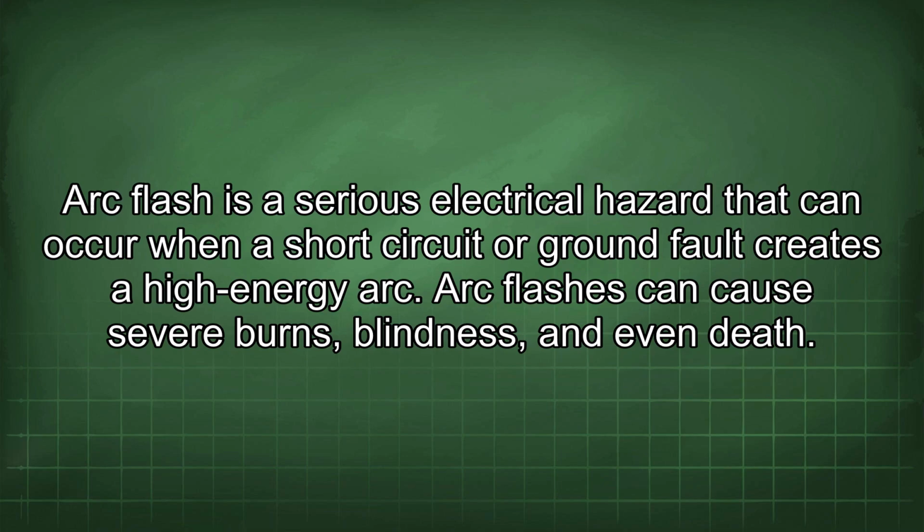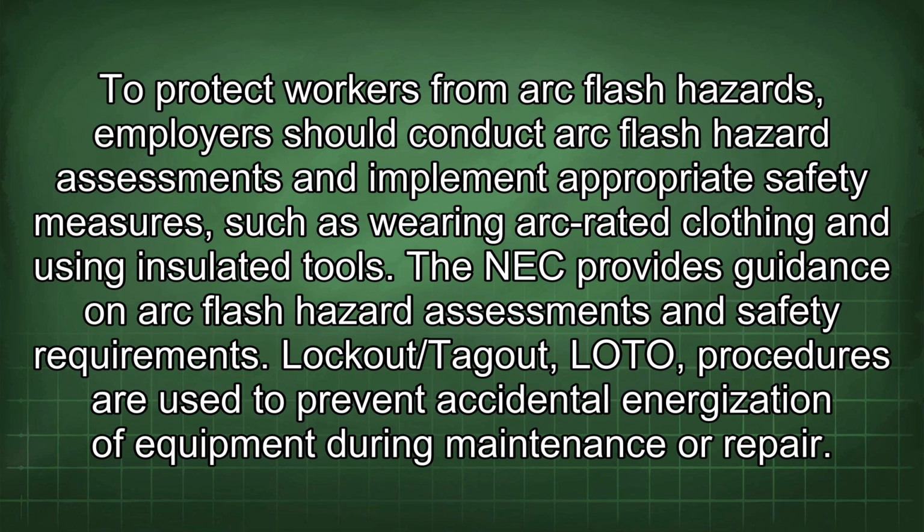Arc flash is a serious electrical hazard that can occur when a short circuit or ground fault creates a high-energy arc. Arc flashes can cause severe burns, blindness, and even death. To protect workers from arc flash hazards, employers should conduct arc flash hazard assessments and implement appropriate safety measures, such as wearing arc-rated clothing and using insulated tools. The NEC provides guidance on arc flash hazard assessments and safety requirements.